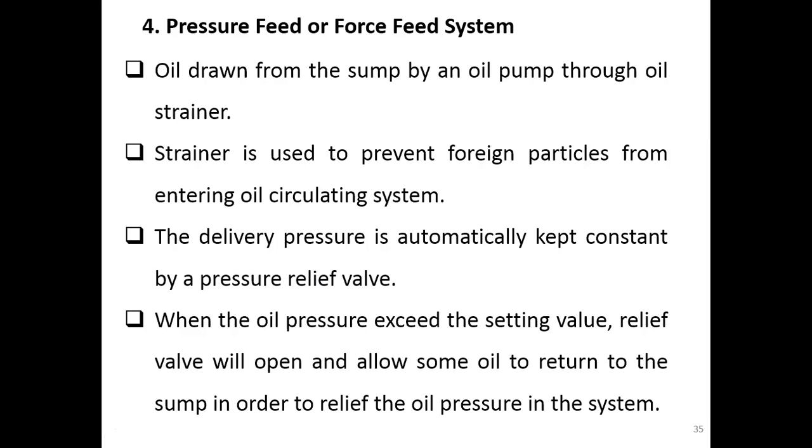If the oil delivery pressure goes beyond the setting point, this relief valve will open, and it will allow some of the oil to flow back into the sump in order to relieve the oil pressure in the system.